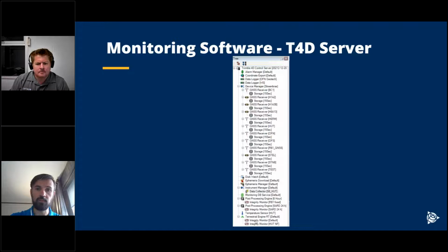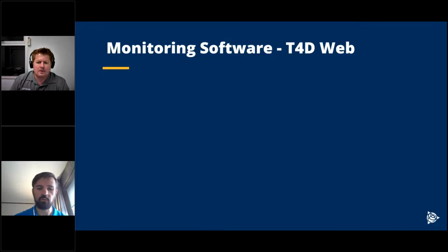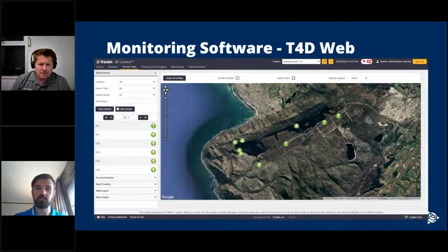Is that to check if there's movement in the position of where the total station is located? That's correct, because if you have movement in your total station, that movement will be translated to your monitored points. So it will look like all your monitored points have been moving, but essentially it's your total station that's moving. Gotcha. So it's kind of like two different networks, one to monitor the structure, but one to also verify that what is monitoring your reference isn't moving as well. That's correct, yes.